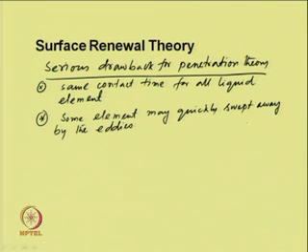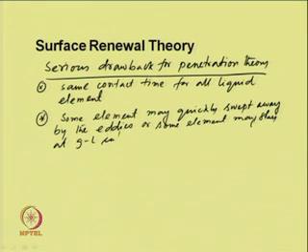Some elements may be quickly swept away by the eddies, or some element may stay at the gas liquid interface for a longer time. So, there is an age distribution of the fluid elements in contact with the gas at the gas liquid interface.